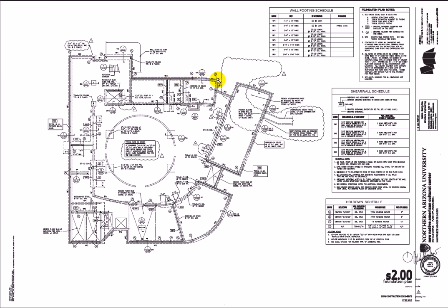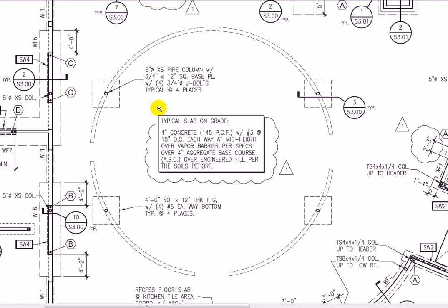Remember from the general notes they had to be 2'6" below the exterior grade or the finished slab. In this case the exterior grade was lower. So that tells the contractor how deep to go. You'll note on the drawings it didn't give any elevations, which puts a lot on the contractor to figure out. So we got those footings. We have these little spread footings here. Let's zoom into the middle and see what's going on. So I see this one here looks like a footing.